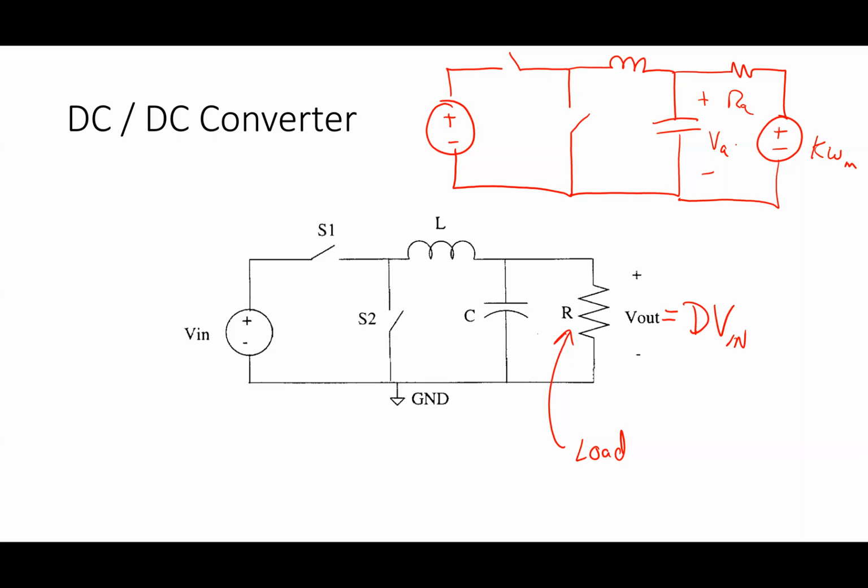All right. Problem 4 basically is just very simple DC motor stuff. And then it basically says, well, I want to change the voltage. You basically have to tell me, okay, what does the duty ratio need to be to get the voltage I want? What you're changing is the width of that pulse, right? And we're just utilizing the fact that if I have a low pass system, I can use this lossless set of switches to put an AC waveform into that thing. And then the dynamics of my filter here just get rid of all of that AC stuff. All right, that's it.